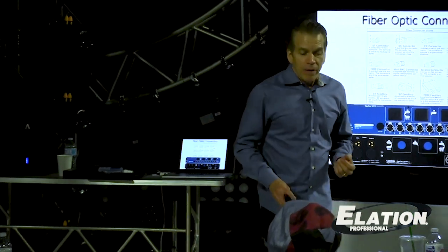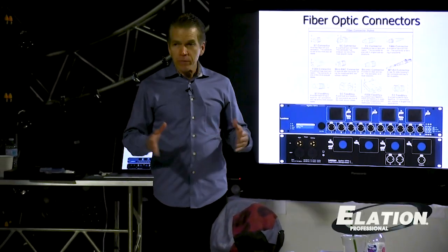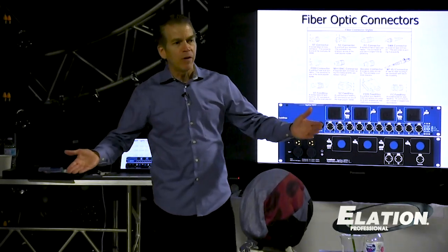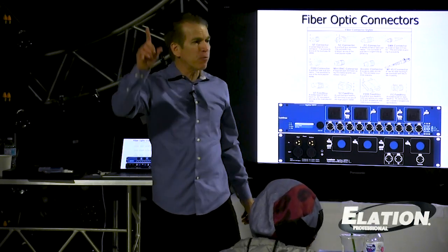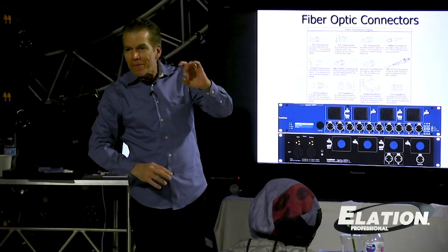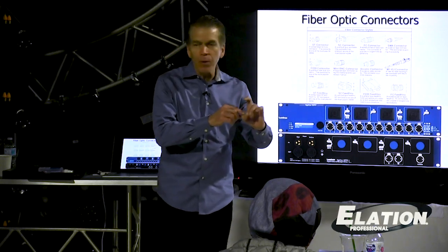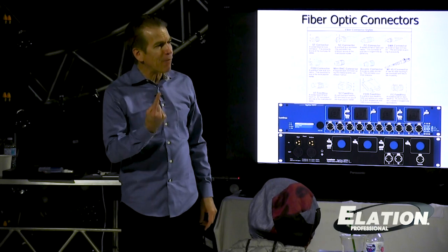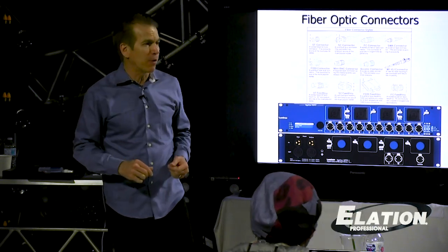If you think about the way analog audio used to be transmitted, you had a mixing console with multiple channels, 96 channels or whatever, 148 channels, whatever, and you're sending that to the amplifiers which live by the stage. And so you used to have big, thick audio snakes that had multiple pairs of conductors in it. That's being replaced by a single Cat5 cable, in a lot of instances fiber instead of copper.